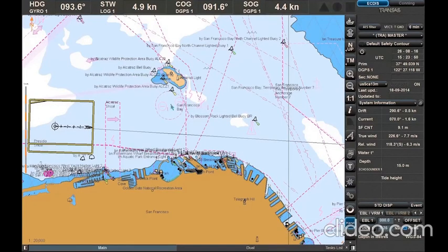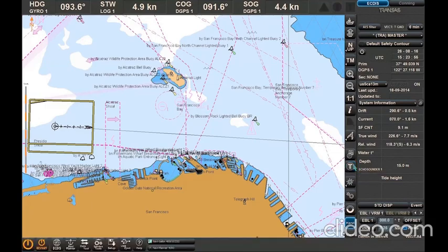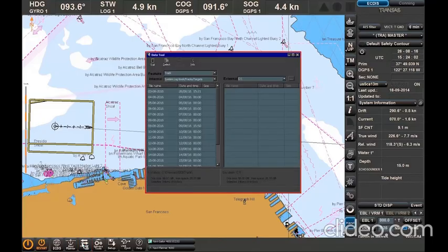Data Tool Utility. Click the Transas integrator from the ECDIS task and select Data Tool. The Data Tool Utility window allows the following operations: to copy or move the ECDIS data into an external carrier and the other way round, to delete data from the ECDIS program, to view and print out archive data.